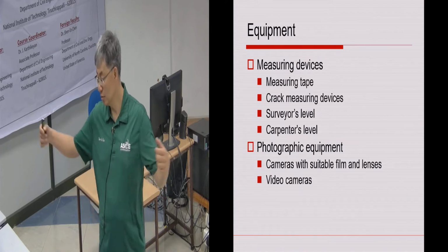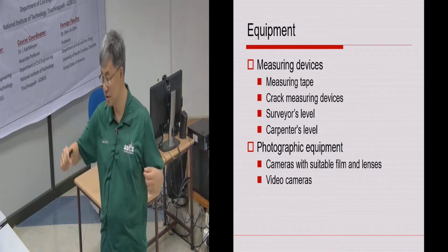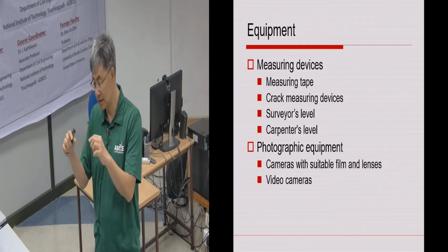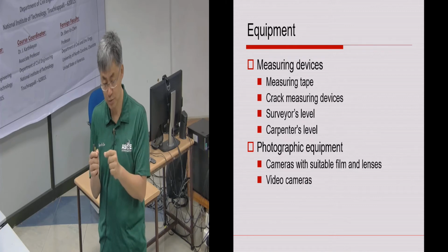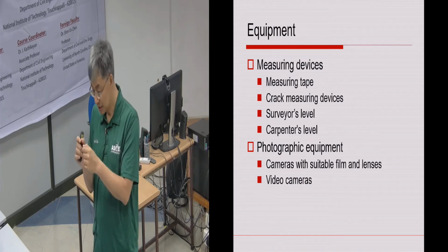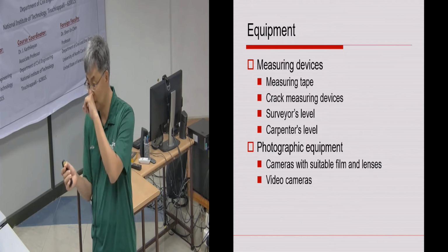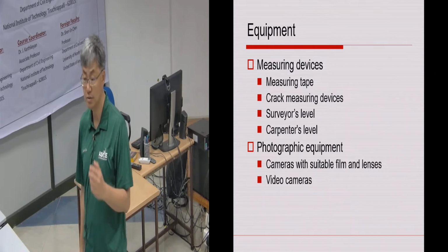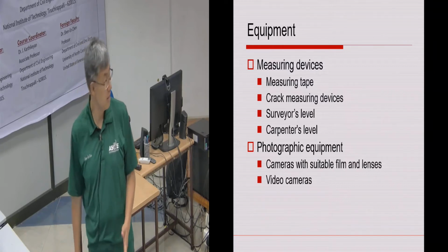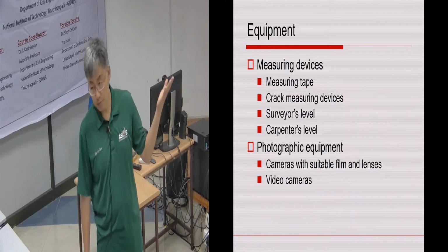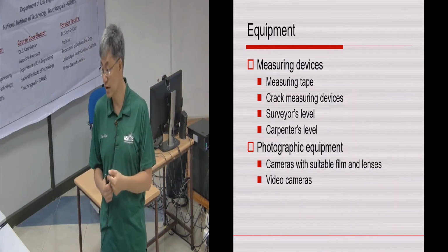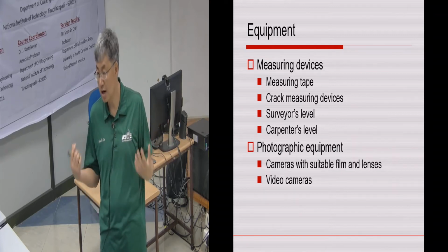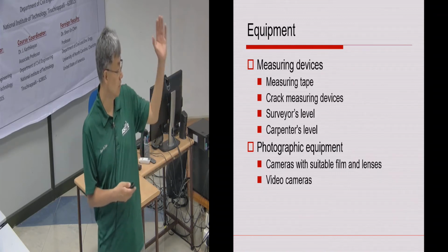So you want to know distance, so a tape measure is definitely needed. And then there is a transparent plastic thing, I think I left mine with CN as well. It's called a crack meter. It can measure the crack openings of concrete. Those are very handy things you can put in your pocket and carry to any inspection. Those are the basics. And then a camera. Sometimes you may require surveying tools, but those are a little more costly and hard to carry with you. So those are the very, very basics.